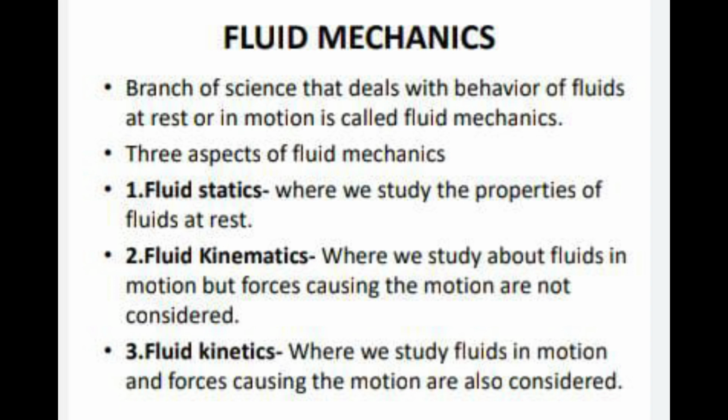In fluid statics, we study the behavior of fluids which are at rest, or we study the various properties when the fluid is at rest. Second one is fluid kinematics. Fluid kinematics is the branch of science that deals with the behavior of fluids in motion where the forces causing the motion are not considered. So we just study the displacement, velocity and acceleration of the fluid particles.